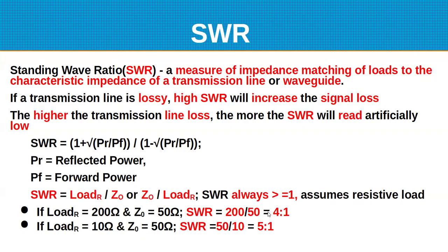So even though in reality at the antenna it might be an SWR of 5, it may only look like 3, and may really only be 3 at the receiving or transmitting end. And that's where you care about it. So you don't want to blow the transistors. Now, if it was a tube type radio, it's not as big an issue. They handle SWR pretty well.